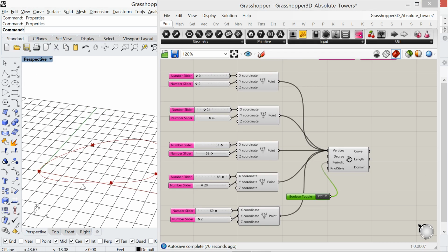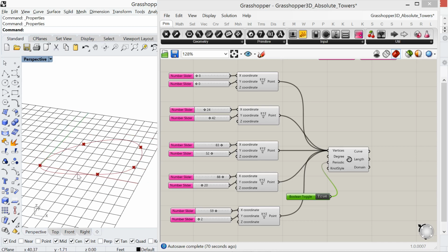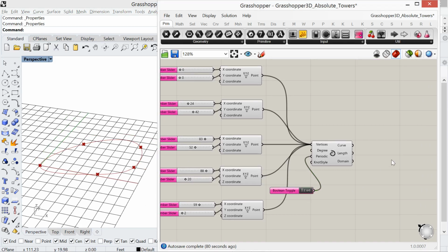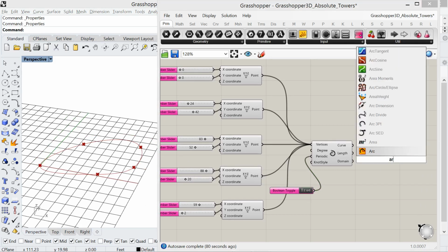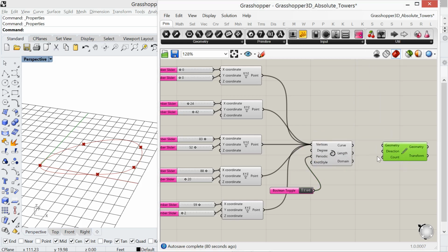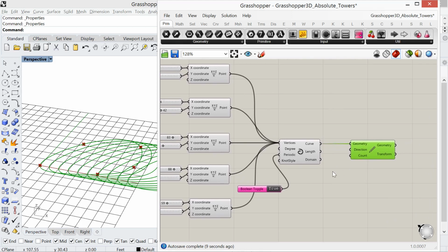So a skyscraper is basically an array. It's an array of, I'll call them floor slabs. So we're going to go ahead and make that array of floor slabs. So I'm double clicking and typing in array, and we're going to choose a linear array. The direction that we're going to array, by default, is set to the X direction. You see this array going horizontal to the right in the positive X direction. And I'm going to want that array to be in the Z direction.